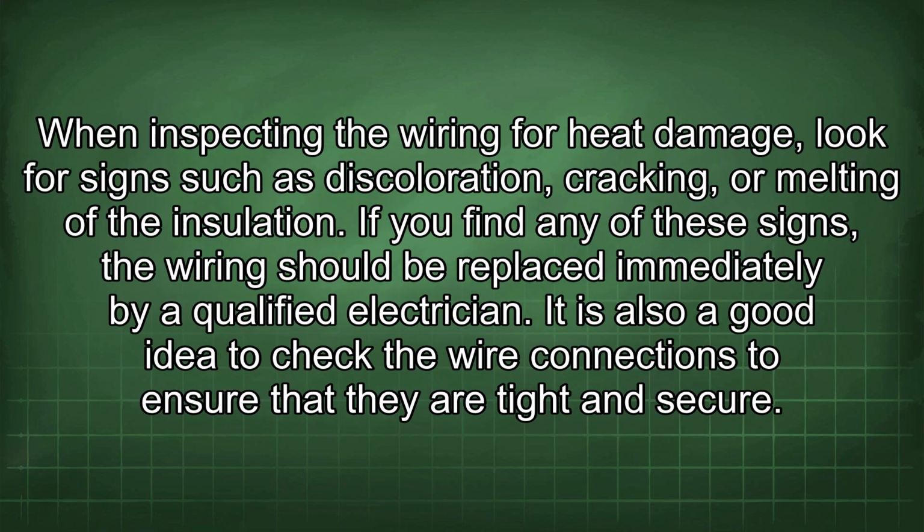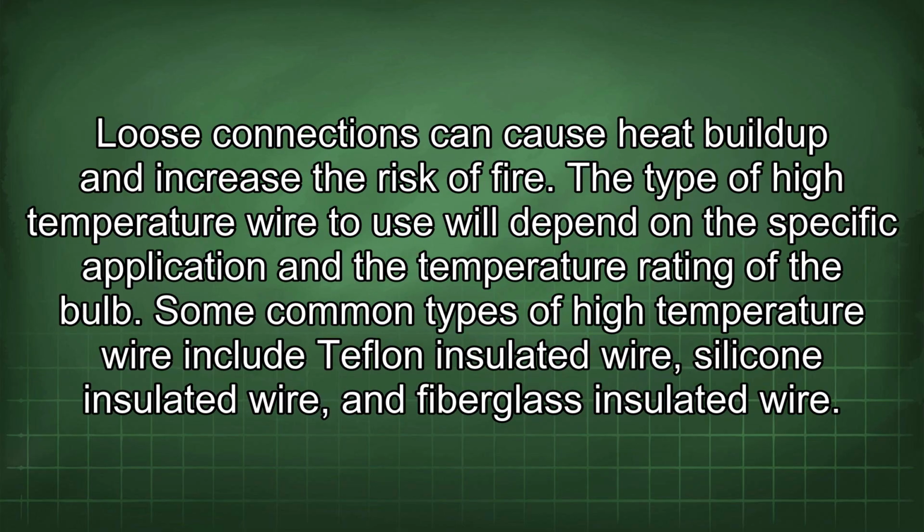When inspecting the wiring for heat damage, look for signs such as discoloration, cracking, or melting of the insulation. If you find any of these signs, the wiring should be replaced immediately by a qualified electrician. It is also a good idea to check the wire connections to ensure that they are tight and secure. Loose connections can cause heat buildup and increase the risk of fire.